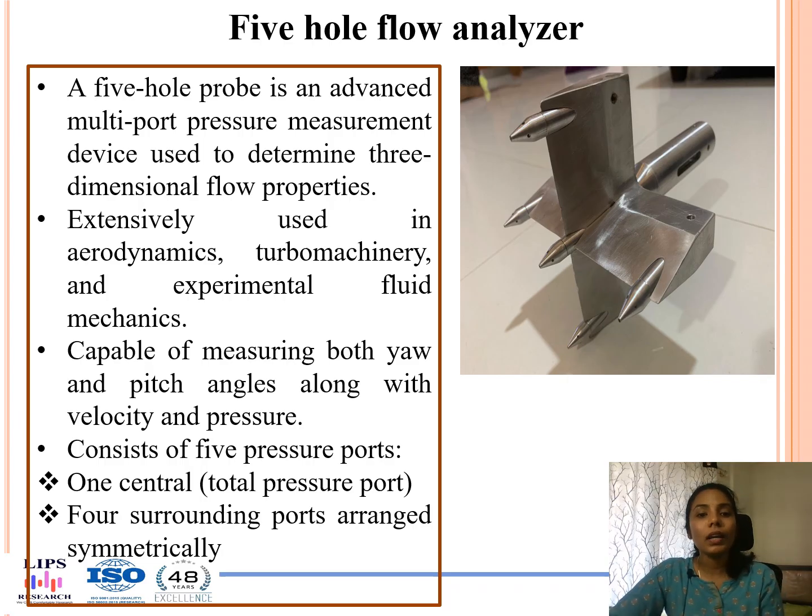Now, the key advantage of this instrument is that we will be able to measure yaw angle, which is the horizontal deviation of the flow, and pitch angle, which is the vertical deviation of the flow. Along with it, we will be able to measure the velocity magnitude as well as the pressure component. So it provides a complete picture of the flow in 3 dimensions.